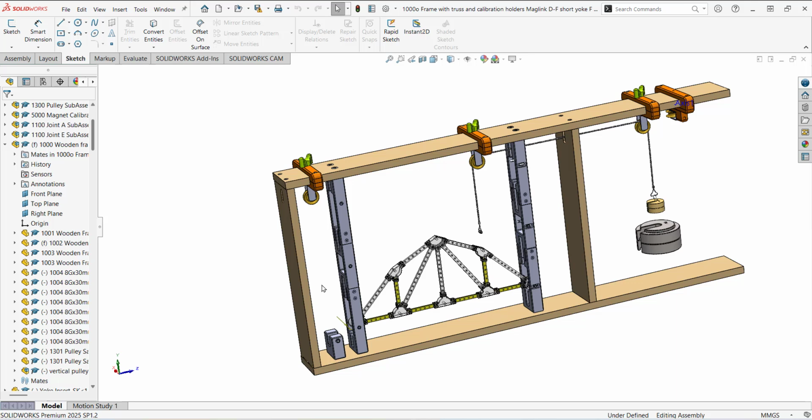Once you have that number, you compare it with the estimated load in this member due to the gauge load of 16 Newton, and you find the magnification or shrinking factor. That factor will tell you how far you have to go with your drop weight to get exactly the same load developed here.